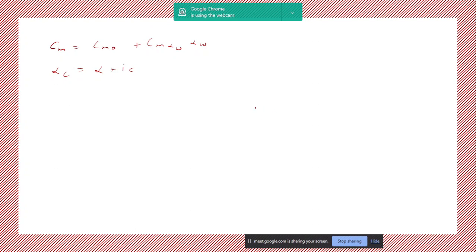And if the wing had a wing setting angle, this alpha would be alpha wing minus i wing, right? Your effective angle of attack would be alpha wing minus the wing setting angle. But in our case, this wing setting angle is 0. So alpha is equal to alpha wing, but I will just write it as alpha wing here. Okay, so your alpha seen at the canard in terms of alpha wing is this.